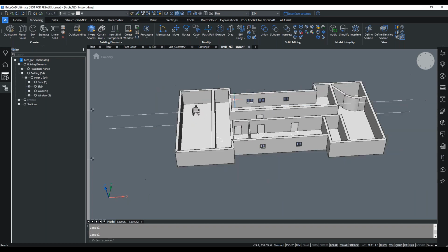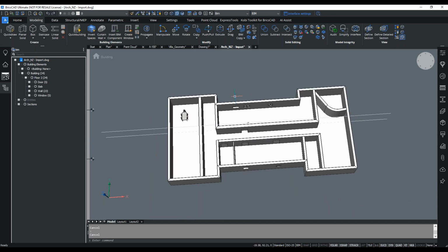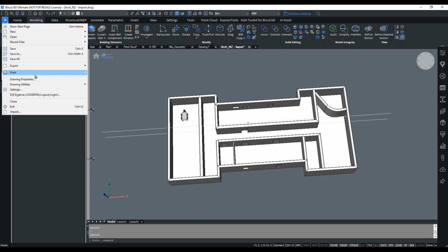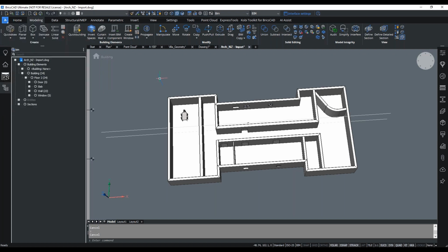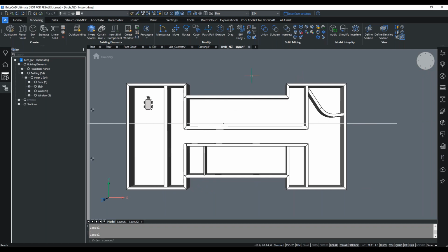So what we'll do instead is focus on how we're going to generate our spaces and our sections and everything else for our plan views. Because we could easily go and select File, Export, and Export to IFC. So for the Scan to BIM side, where we've done the basics to get started, what we're going to focus on now is the Scan to Plan side. So let's run the BIMify command. So we go back to this view here, we type in BIMIFY.